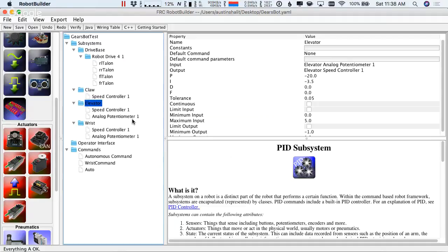So you could just say drive the motor till we're at the set point, but then what happens is there's inertia, and the thing drives way past the set point, and you miss it. So what all this control stuff does is it's an algorithm for letting you drive it right to the set point and stopping and holding it there. And that PID stuff that Austin was talking about, that's these numbers here. You can just type in the numbers and it will use them. And if you look at the video, it explains where the numbers came from.